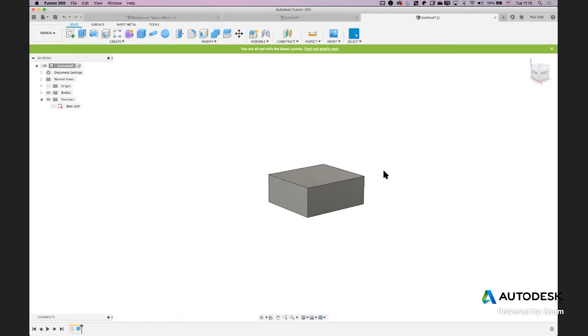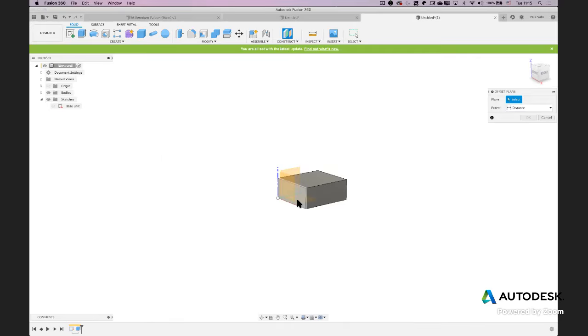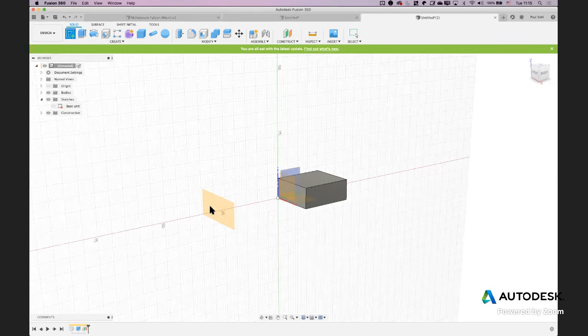Next, we've got the actual 1/4" jack where it needs to connect. What I'm going to do is click on this face here, and I'll pull this out because I want to create this part a little further away from the piece so that I can bring it all together afterwards. Now, a standard 1/4" jack usually has some kind of hexagonal port on it. This helps us screw them into place as well as be a quick visual identifier. So we're going to create another sketch here.